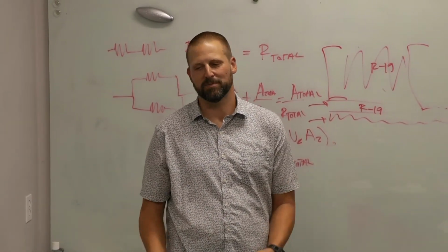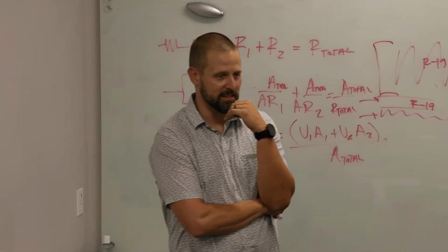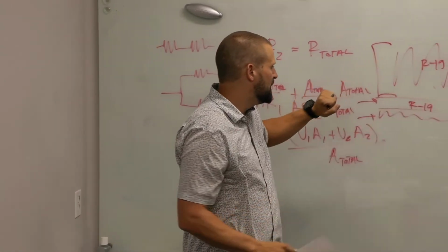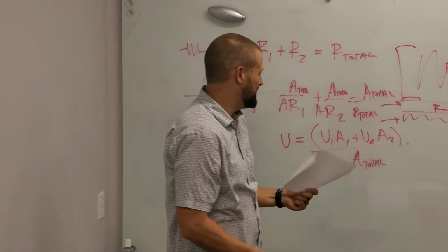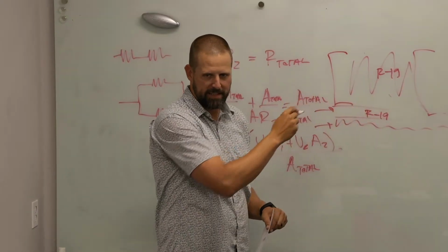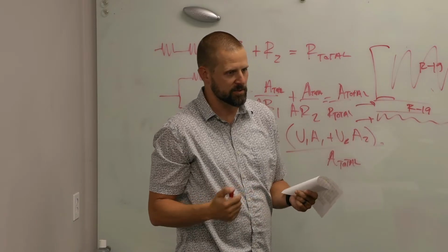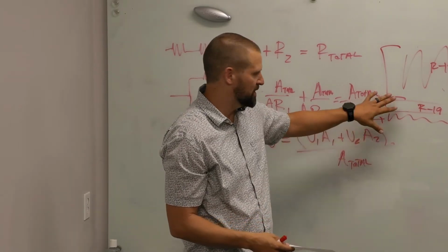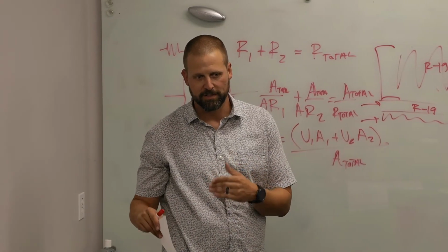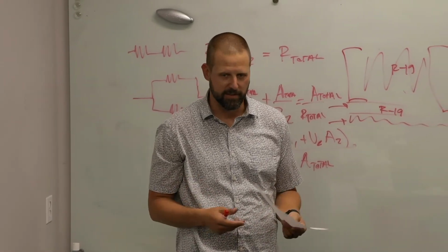I should blame architects, because we deal more with architects. Architects will do the same thing. We'll say, hey, you need R19 continuous insulation, and they'll put it between the studs. Also, the detail for building this, and like putting the clips on here and pinning this, is a lot more work than what was done 20 years ago. It's just a harder detail to build. I think it's much more common in new construction now than it was even 10 years ago, but it's still kind of a new thing to our industry.